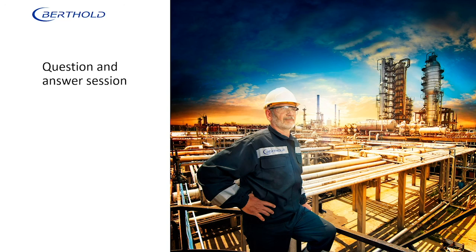Okay. Would a 2-point calibration of empty mold and shutter closed be adequate for linear calibration? I would say yes, because the customer or the users are not really interested in having a good precision down in the mold at 1, 2, 3%. They're only interested in being able to start the caster. So I would say yes, that would be okay.